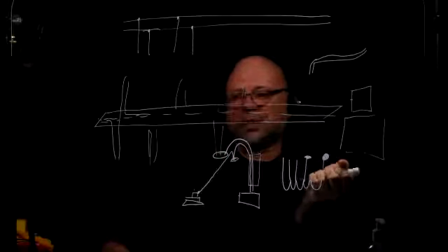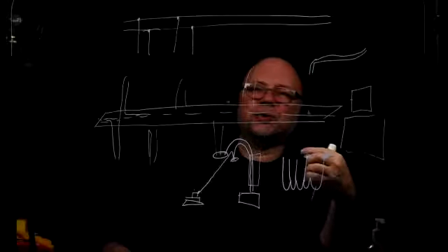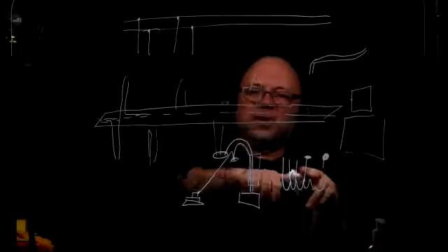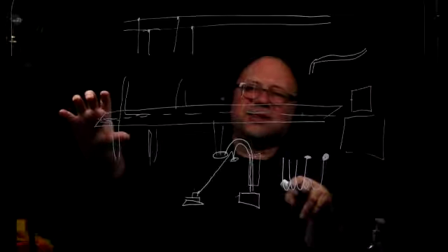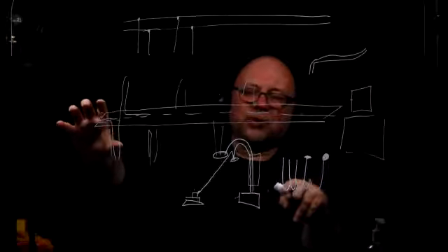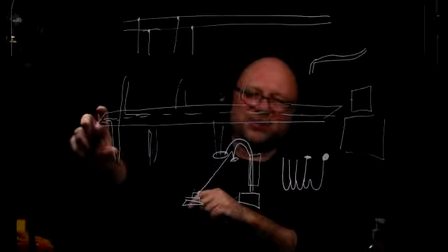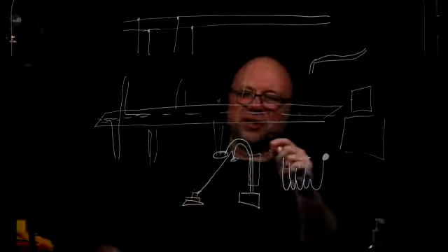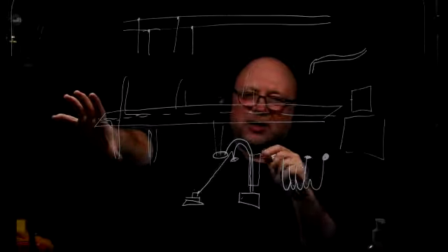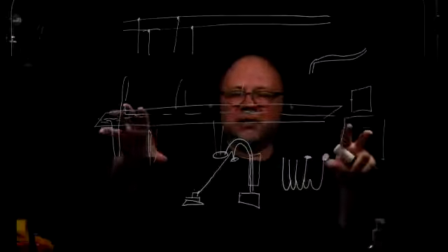If you study things a little bit further, distortion is basically almost coming close to a DC signal. Right? If you apply a DC signal to a coil, it is not a very good situation for the coil. Coils provide very low resistance to DC, and they can burn out. So you can burn out a 100-watt speaker with a 10-watt amplifier. Right? The best thing is to match 1 for 1. It's the best scenario.